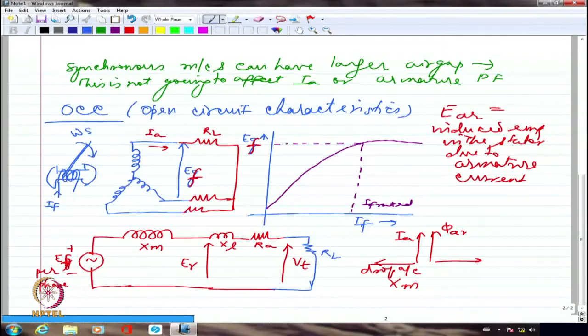So, when the rotor winding is looking at the stator flux or the air gap flux, which is the resultant of the original revolving magnetic field flux created by the rotor, plus whatever is the new flux created by the armature current, both of them are rotating at synchronous speed. So, obviously, the rotor will look at that field as though it is stationary, because the rotor itself is rotating at synchronous speed. The relative velocity is 0. So, the rotor will not...